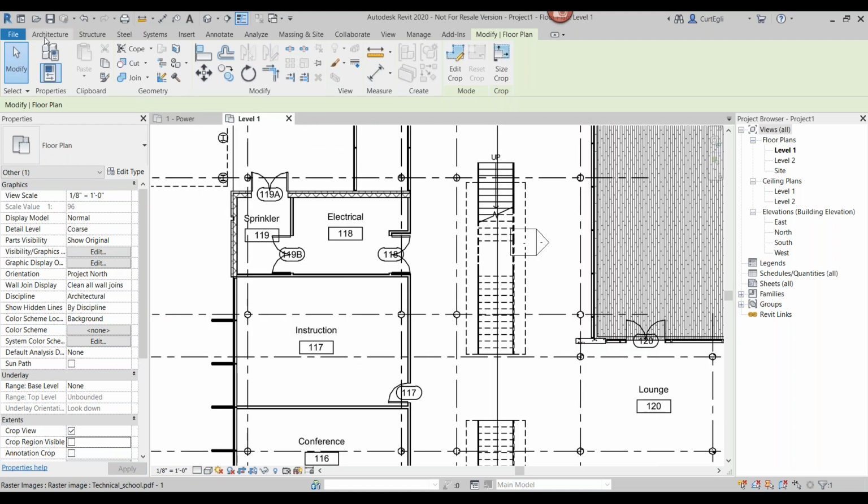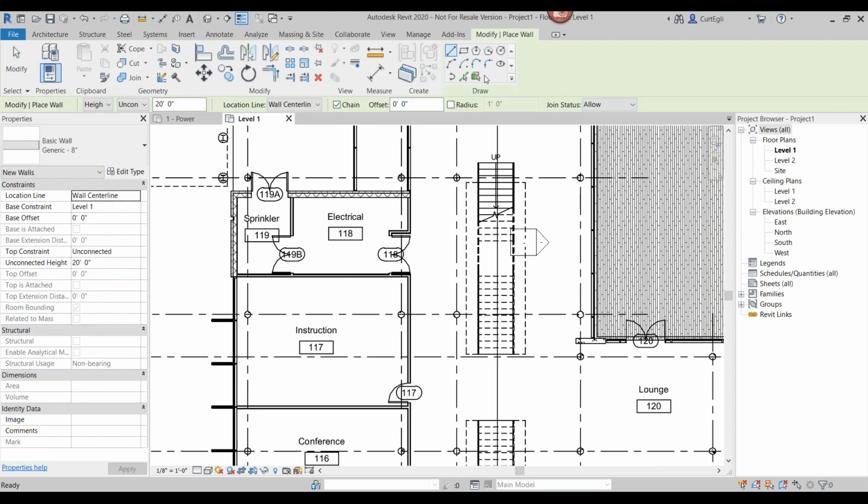Additionally, because we have snaps on, I can say that I'd like to use pick lines or just start to trace over the top of it as well. So let me do finish face interior here and just do like that. And, here, let's do this one. Just give you kind of a sense for this. So here I am, I'm starting to convert it into Revit entities as well, right on top of it. So anyway, that's PDF that we're working with.